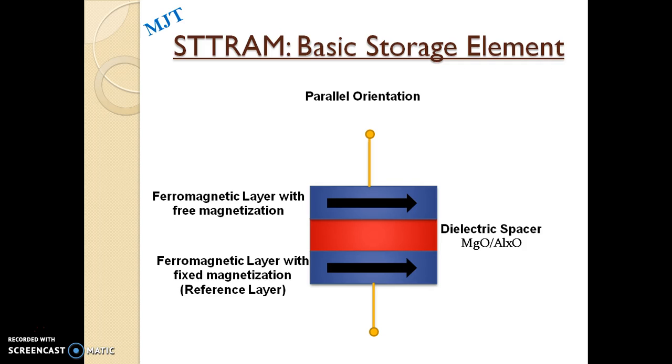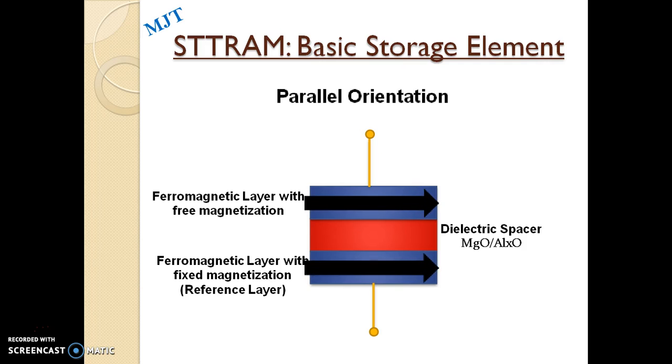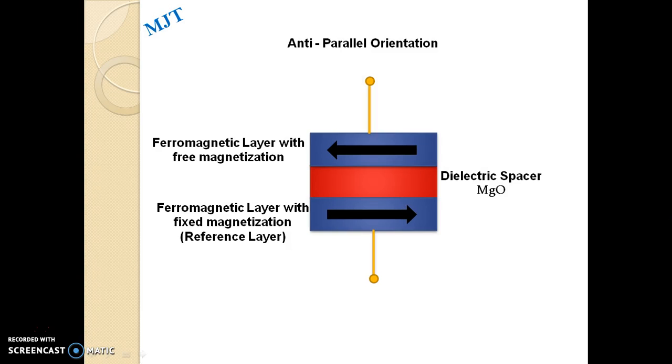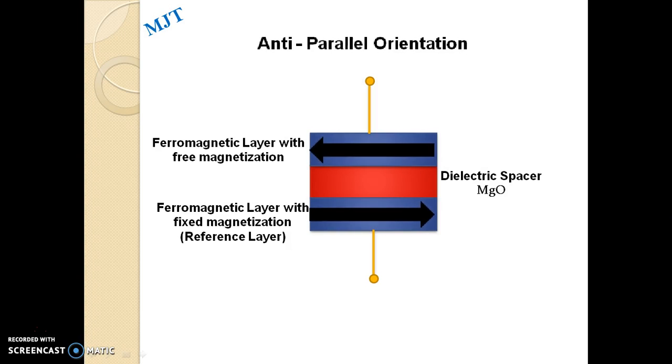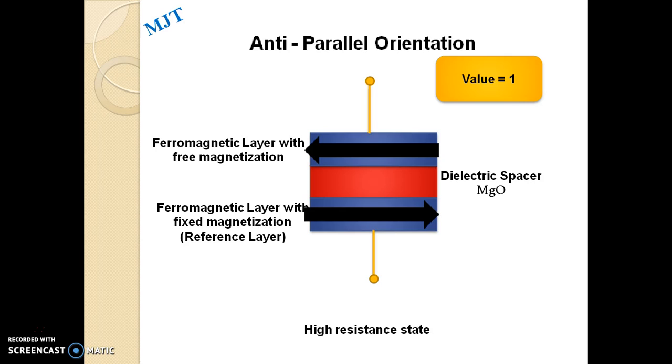If the spin transport is in the same direction in both ferromagnetic layers, the MTJ presents a low resistance and is designated a binary value of 0. A high resistance is seen when the spin direction in both ferromagnetic layers is opposite or antiparallel. This orientation corresponds to a binary value of 1. So, in STT-RAM, data is read as tunnel junction resistance. The resistance can be easily implemented using a differential sense amplifier at low cost.